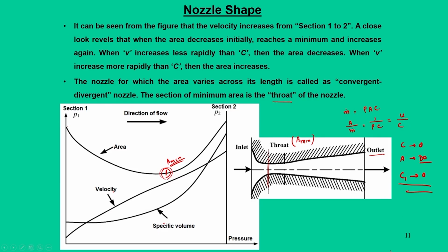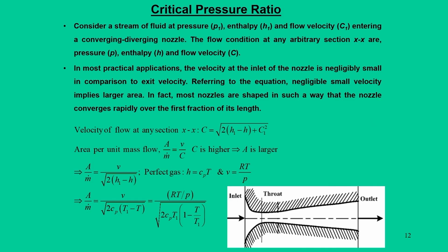So, we get what our inlet shape and outlet shape should be, and this expression gives you the throat of the nozzle, the minimum area. These mathematical expressions are now sufficient to analyze further and quantify what happens to velocity and other parameters.